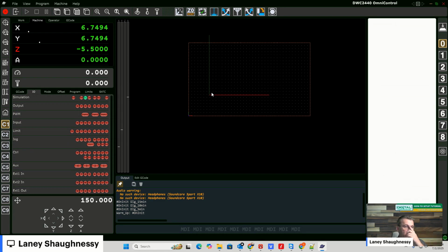Everything is the same as what you've always been used to in the Planet-CNC TNG software as far as the TNG software buttons. But there is going to be a new set of buttons down below, the C1 through C9 here. Now, depending on your resolution, you might not see all 9 buttons. If your resolution is set really high, or really low, one of the two, it'll cut off some of the buttons. You'll see just a plus sign down there that you'll click to see your other buttons. But C1 through C9, that's your coordinate systems.